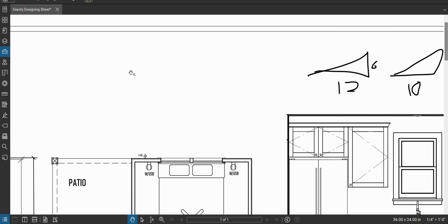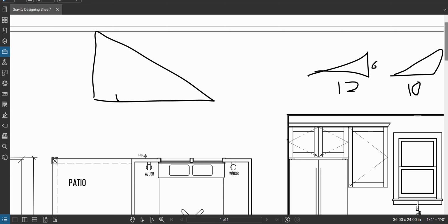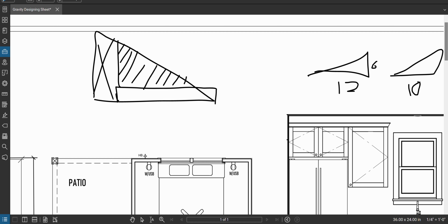Because what I'm doing here is I'm claiming I know, here's what's going on here. This is all the way to the center of the room. Our beam exists. It's going to be a raised beam. Our beam exists right here, and we're holding that piece of that pony wall. We're not holding this, but we know this is 5 feet, right? That's 5 feet. So if I just assume it's 5 feet without doing any math and make my life quick and easy, then what I'm really designing is this, which is slightly more weight.